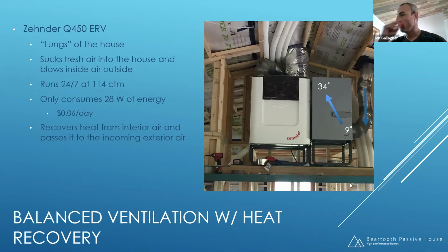All right, so here's an example where this duct right here is insulated now, but in this picture it wasn't. Let's say in the winter we had 9-degree air coming in from outside. It goes through this box, which has a little pump in it and some tubes buried underneath the ground. We steal the ground's heat to preheat this really cold incoming air.